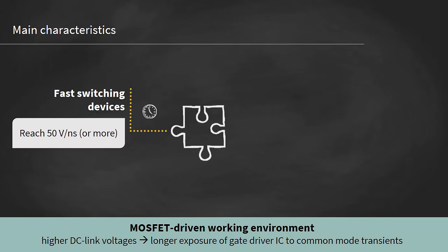And that in a MOSFET-driven working environment, you have to take the higher DC link voltages into consideration. These lead to a longer exposure of the gate driver IC to common mode transients. This will subject the gate driver IC to higher common mode transients.